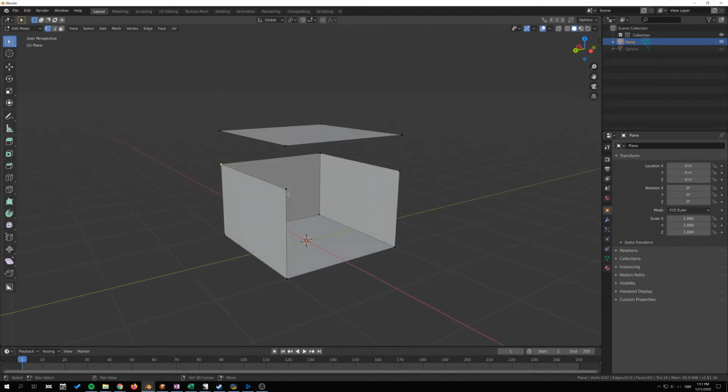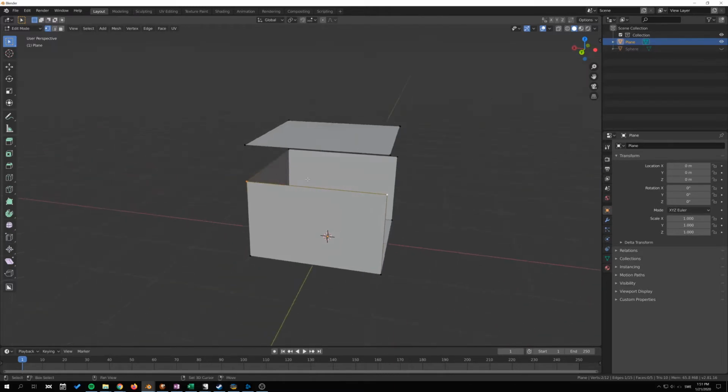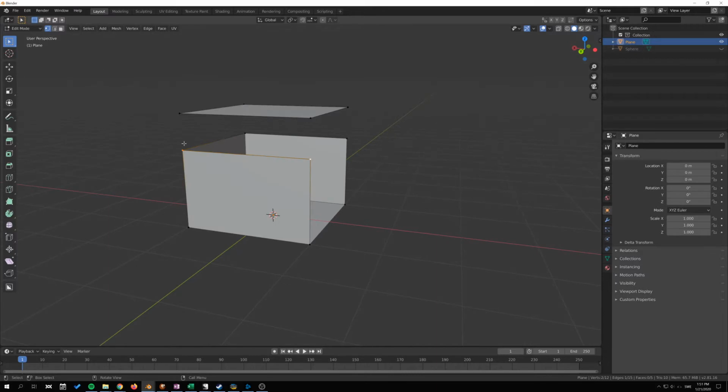And if we have two vertices selected like this and press Alt M, you can see that we get two additional entries there. So let's look at those first. If we have this kind of scenario and we say at first, we'll merge at the first vertex that we selected in our sequence. So we'll merge this way. And if we merge last, we'll merge this direction, just like that.